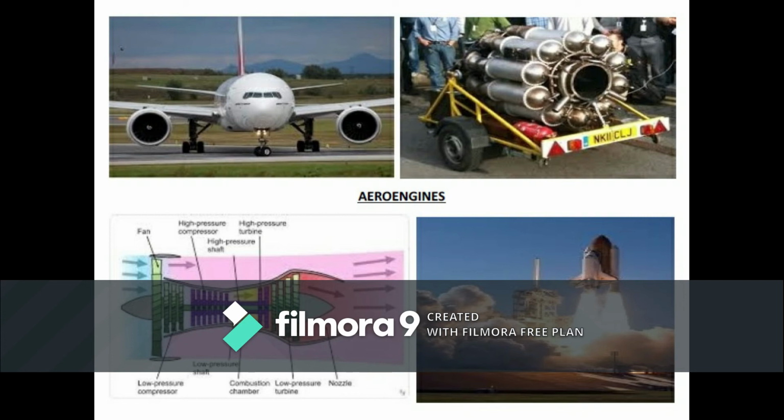Whereas in a scramjet engine, whose full form is supersonic combustion ramjet, the supersonic air which has entered the air intake is reduced, of course, but not to subsonic speed. It stays supersonic, the combustion takes place at supersonic speed, and then a further increase in supersonic speed takes place in the nozzle.